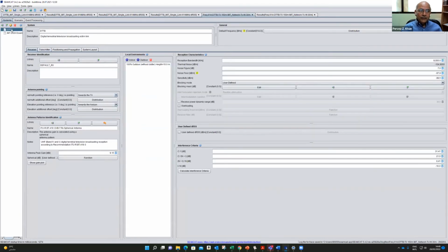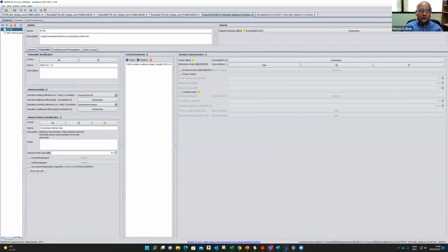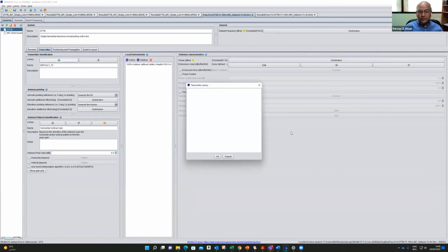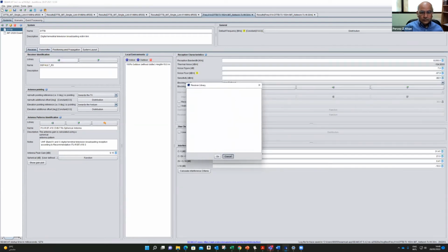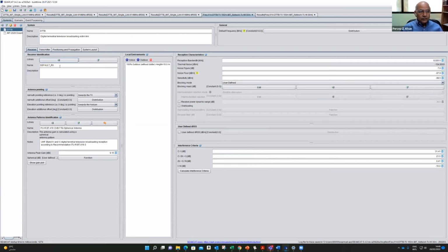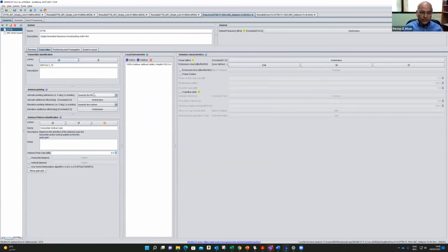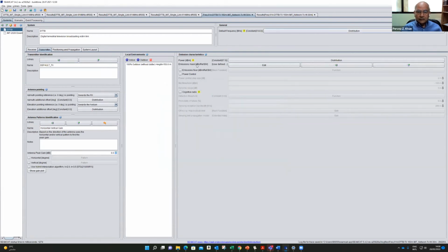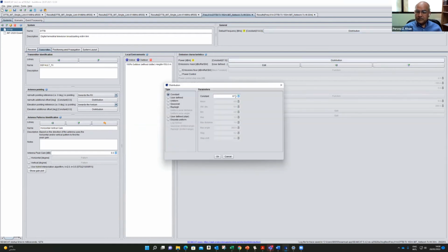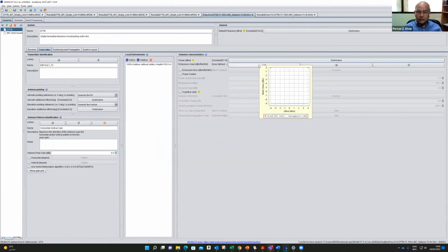So in the network, we have taken a TV system, and this TV system is created. As I said, we create the transmitter. Once we can add the transmitter from here, or if we want, we can use the library. So you can always create a transmitter and define the parameters. You have to select the frequency. In this case, I have taken the lower band, 614 megahertz, and then the power of the transmitter can be defined here, 67 dBm, and the mask also can be defined.